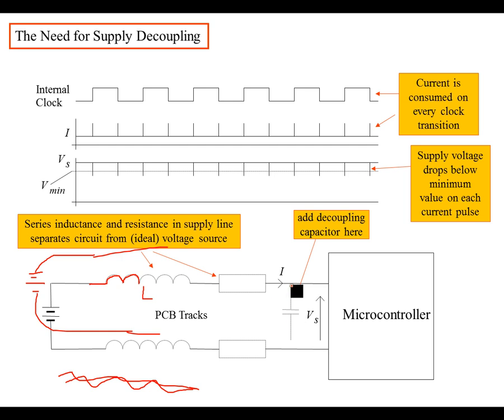But if it's not, another way to circumvent that inductance is decoupling. We call it decoupling the supply, and that's by putting a shunt capacitor across really close to the microprocessor. So if you have your microprocessor here, and these are your pins, say this is your supply, then we want a capacitor as close as possible to this, connected here on one side, with leads as short as possible. If possible, you could have it go under the board, or have it on the back side of the board, just going across it to VSS and then VDD.